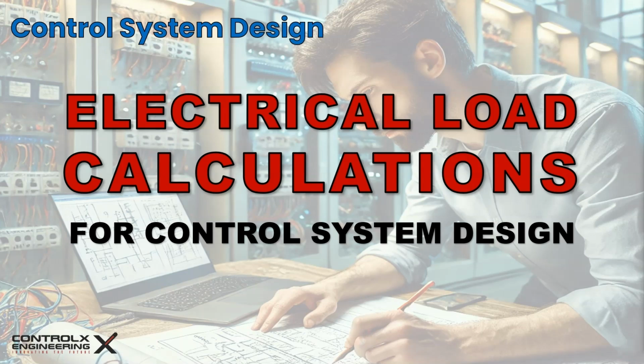First, we'll go over how to calculate loads for both single phase and three phase power systems. Then, we'll talk about how to properly size disconnects, transformers, power distribution blocks, contactors, and other power components based on your total load. After that, we'll discuss how to determine the right fuse size to protect your system. And finally, we'll wrap it up with wire sizing calculations to ensure safe and efficient power distribution. By the end of this tutorial, you'll have the knowledge and confidence to size electrical components like a pro. So grab a calculator and let's get started.